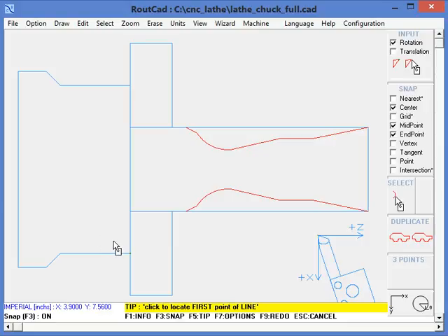But the good thing about drawing objects with the keep out of routing enabled is that when we draw other construction lines on it and we want to select this line to route them, the application will never select a line that is keep out of routing line. So we can have on the same project lines or features that are keep out of routing and other features that are construction lines that we intend to route and then eventually export to G-code.